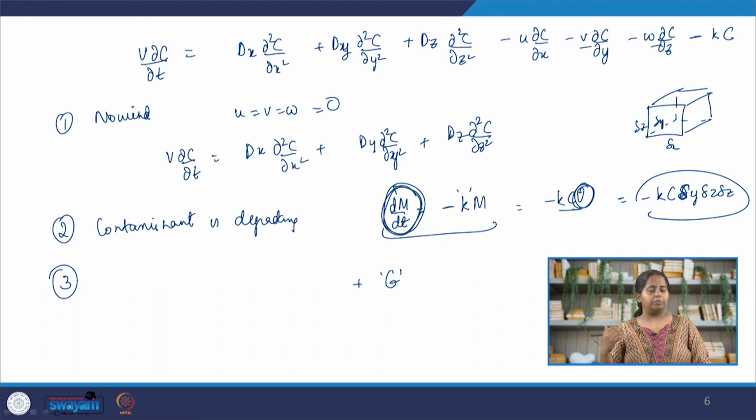So, the generation can be per unit area. Since our parallelopiped area is del x, del y, we need to account for that. The emission is coming in from here, the rate at which it is coming in. Let us say per unit area, a unit of mass is coming in. So, the bottom of this parallelopiped will be getting a del y del z per unit time, and then we need to also find out m out. We are going to use Taylor's expansion like we did earlier, and then we will get a term. So, in that case we will have to include a generation term here.